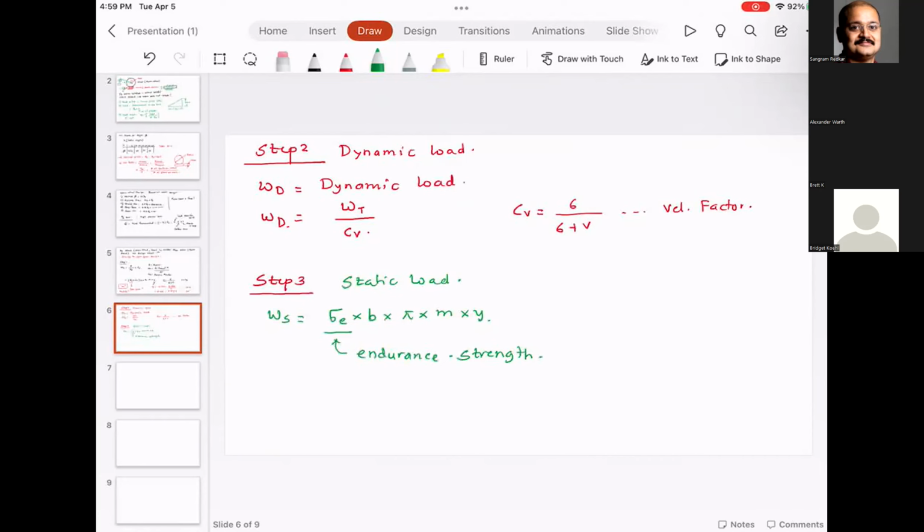Because when you have steel to phosphor bronze, the coefficient of friction between those two contact surfaces is significantly lower compared to steel and steel. And the other thing that happens is when you have steel coming in contact with phosphor bronze, after some time, basically those two wear into each other.